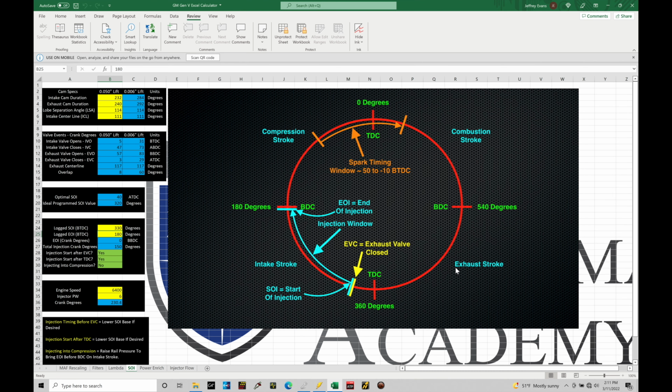And when we're typically referencing our Otto cycle, 0 degrees is normally referenced as this TDC point between the intake and exhaust stroke. And then as we move forward here, this would be 180, this would be 360, this would be 540, and then coming back around again, this would be 720 or 0 degrees and starting off the Otto cycle again. Now in this situation here, what we're going to be finding is that the values are referencing the same type of operation as our start of injection. So start of injection references points at 0 degrees, this is at 360, and we know we command that start of injection point somewhere in the range right here, ideally, and it's going to usually be after exhaust valves closing, so we keep the fuel.